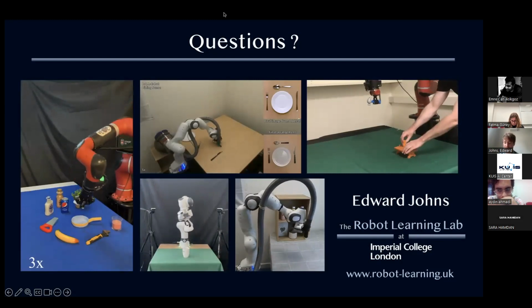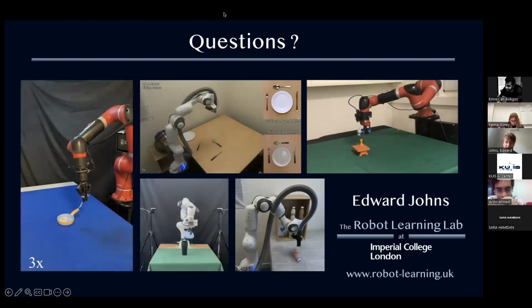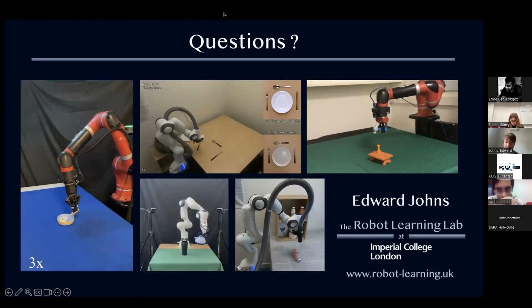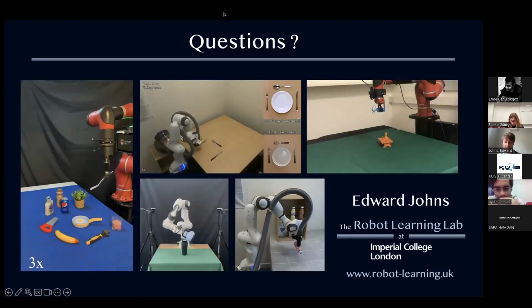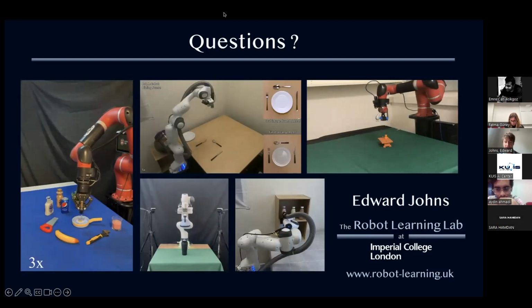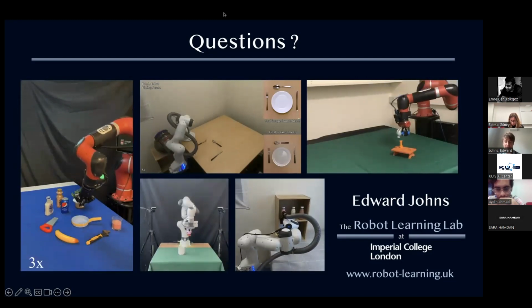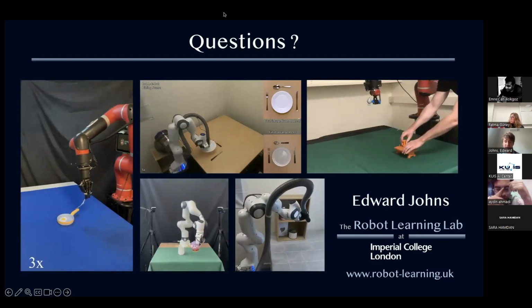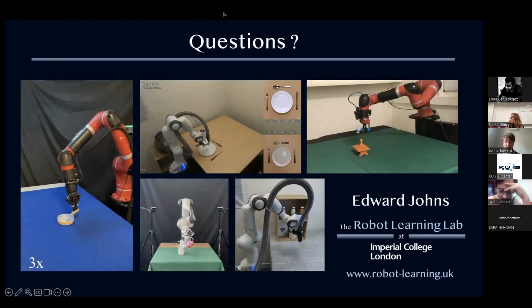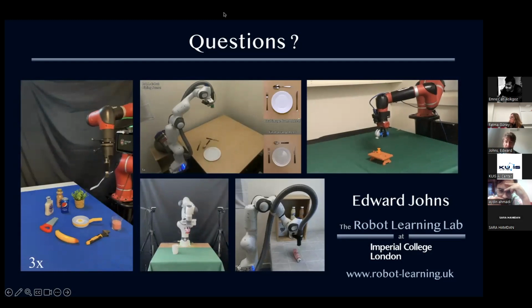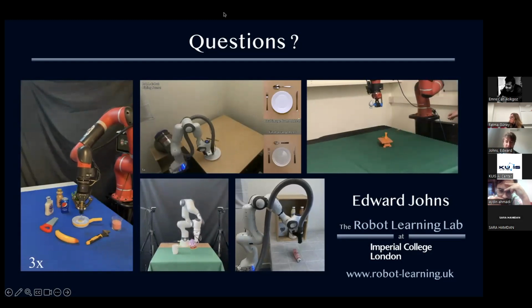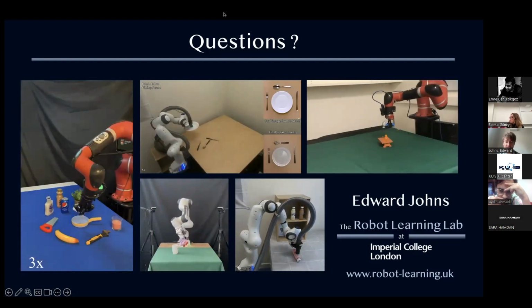One is you can represent object poses. You can use a computer vision front end to your pipeline that will then reduce the dimensionality from image space down to pose space. And then you might be able to represent objects in terms of a 6 degrees of freedom pose. So 3 translation components and 3 orientation components.